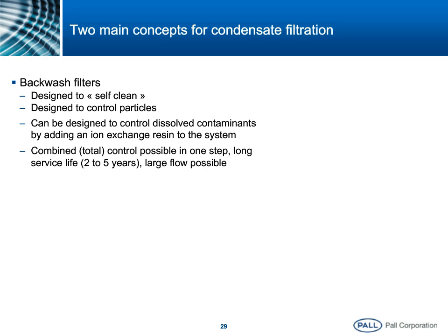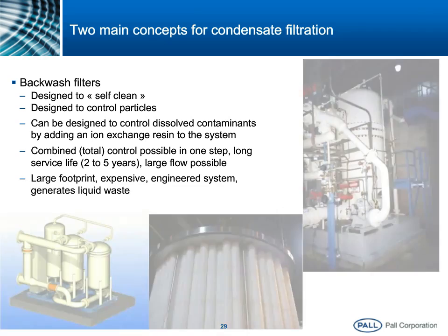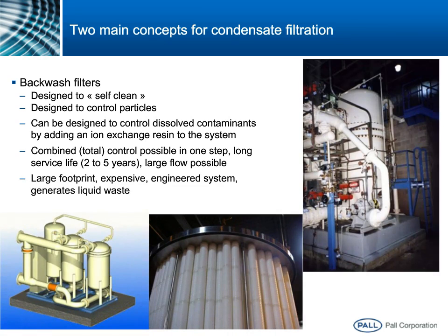The large flows are what usually determine the use of backwash systems. However, typically it's a very large footprint. It's quite expensive to buy and to install. It's heavy capital equipment. You can see the size of them in the pictures. They do generate liquid waste, because that powder plus the particles, when expelled from the filter during regeneration, is waste that needs to be handled.